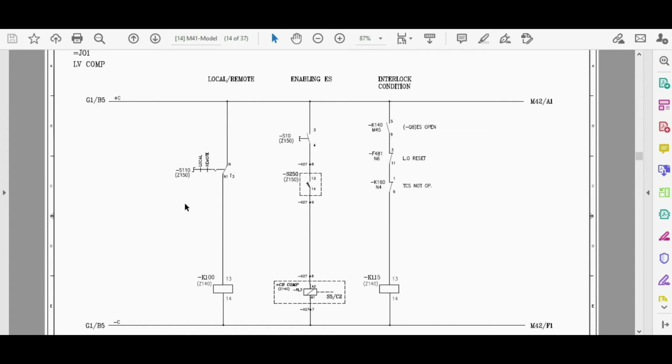And the second one, if operators are on the other side, I mean the control room or upstream system, they can send the command by the network communication to the protection relays, and then the binary output of the protection relays can send the command to the circuit breaker. That's why they need to change it to the remote position. In this case, system integration is needed.